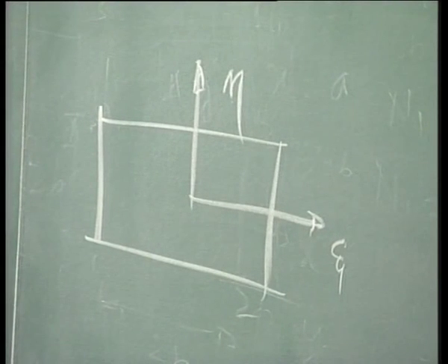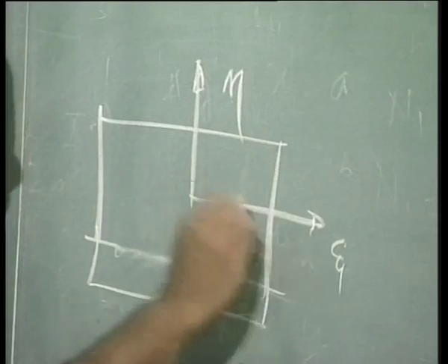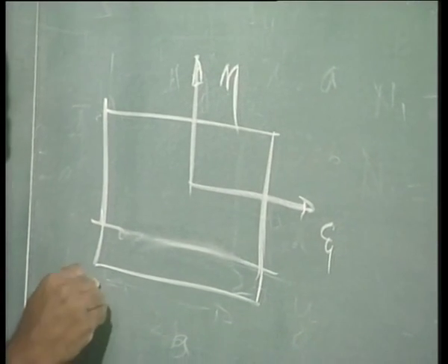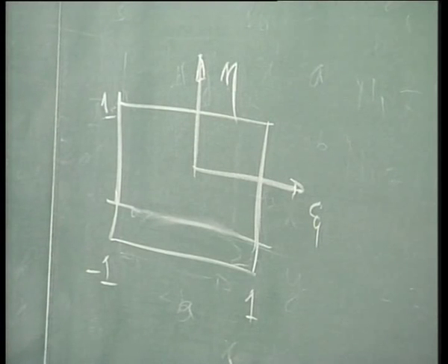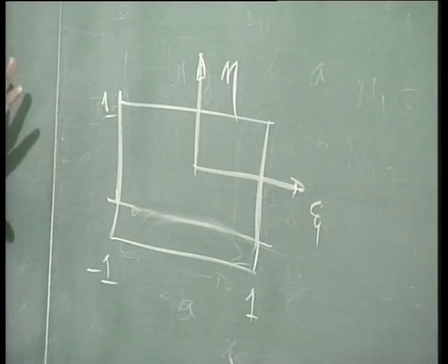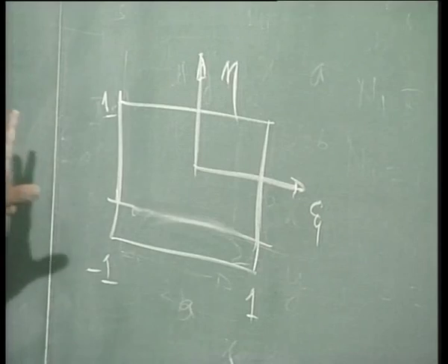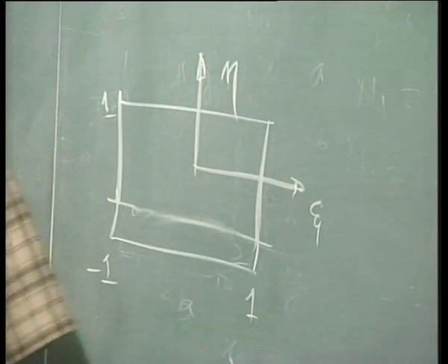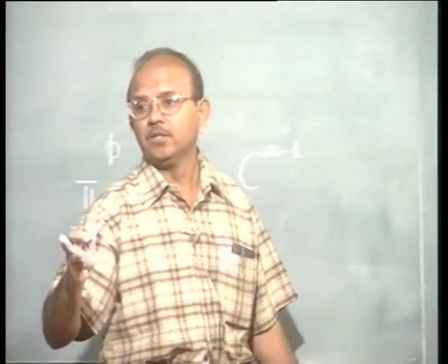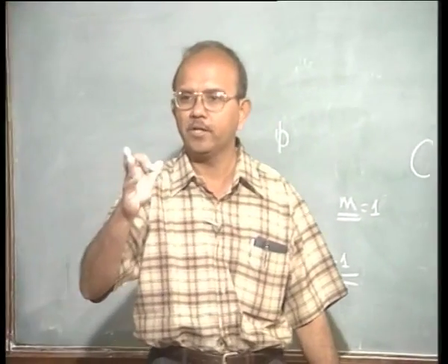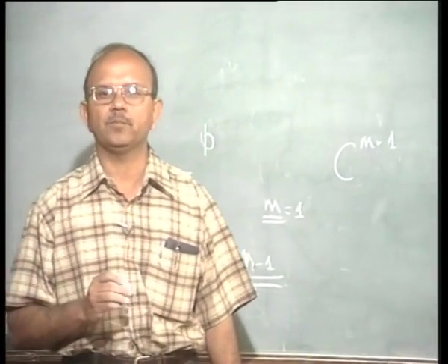It should be more square, and this varies from -1 to +1. Psi eta coordinates, -1 to +1. Write down N1, N2, N3 by inspection method, not by substitution. You can substitute 2a, 2b, but I would like you to write it by inspection method.